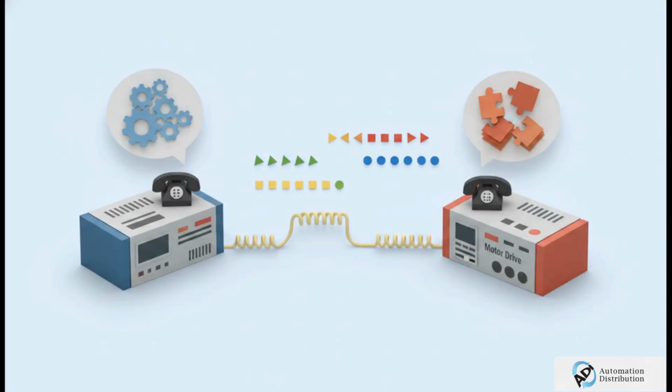Let's think of that Ethernet cable like a telephone line. It perfectly connects the call, right? But if a French programmable logic controller calls up a Japanese drive, well, they still can't communicate without a translator. They're basically just shouting different languages at each other over a perfectly good phone line. The wire just establishes the connection. The three dominant languages actually flowing over these industrial wires are EtherNet/IP, PROFINET, and Modbus TCP. If a device is built natively for one of these, it will not natively exchange I/O data with a controller built for another. Period. I don't care how hard you push that connector in.